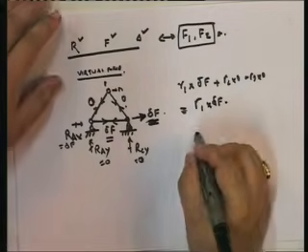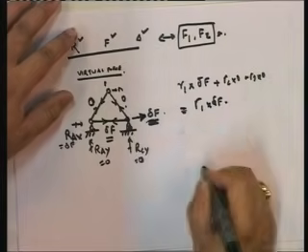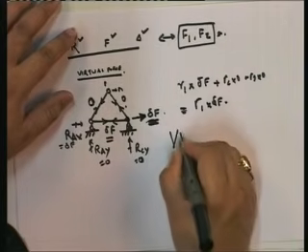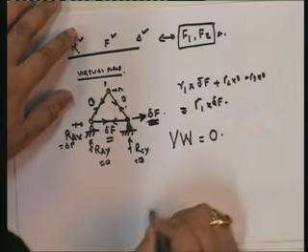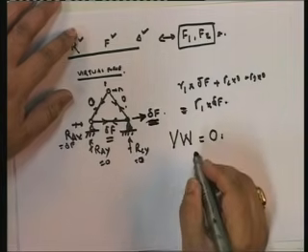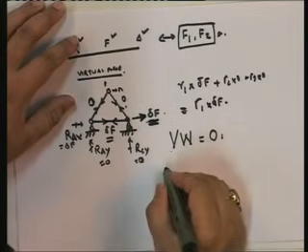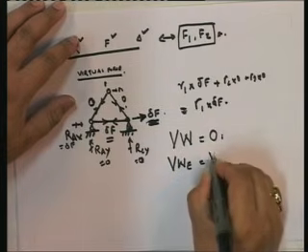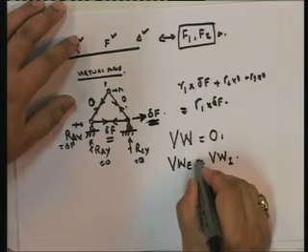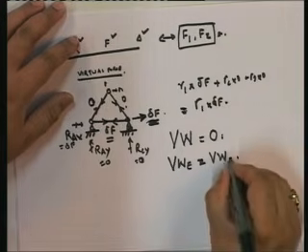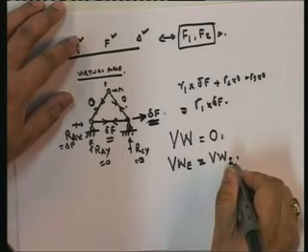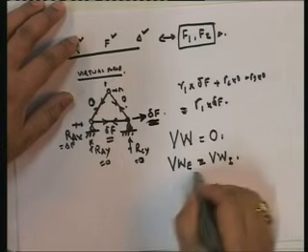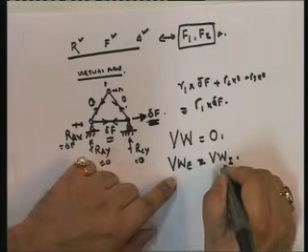Now, if you remember, the equation said total virtual work is equal to 0. We can also write this in another way: the work done by the external displacements is equal to the work done by the internal displacements. How can we write it this way? Because all the internal forces in the structure are essentially reactions to the loads, so they oppose the loads.